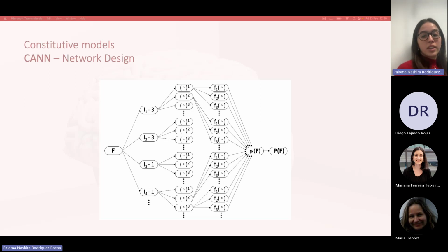The connectivity of the network has been modified to decouple the invariants to satisfy polyconvexity. The activation functions F1, 2, and 3 in the last layer would only be thermodynamically admissible ones. And the output is the free energy function, which would be a function of the original deformation gradient tensor, from which the stress would be calculated in a post-processing step, therefore satisfying thermodynamic consistency.